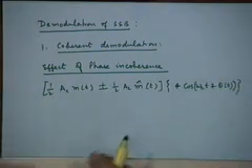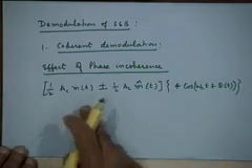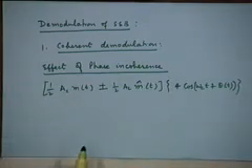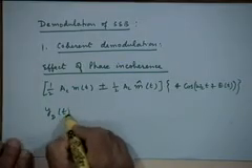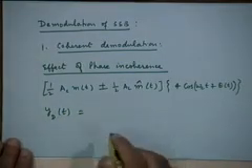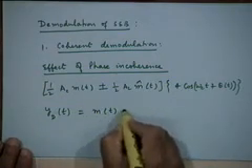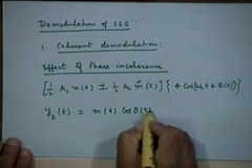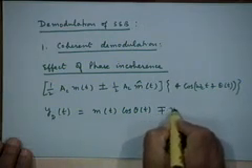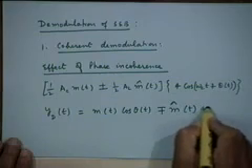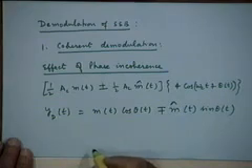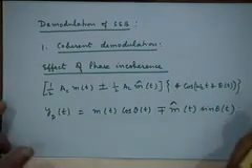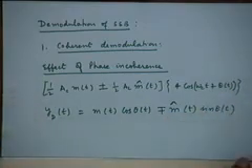Okay, so if I do this exercise, multiply these two, pass it through the low pass filter, it's a very simple trigonometric exercise. I'd like you to do that yourself, and you will see that the demodulator output after low pass filtering reduces to this expression. Simple trigonometry and removing the 2 omega_c terms.